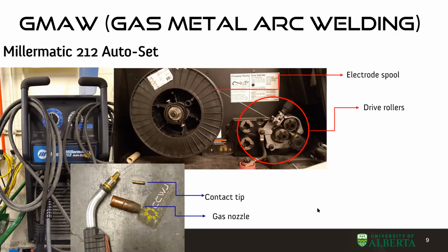So when you put down the electrode to be in contact with the plate, many bad things happen. Number one, you don't conduct electricity through glass until you push so much that you break the glass, and then the contact starts. And if you saw, not only was there an explosion, but the torch started to jump like crazy. That is because of the force of the wire pushing until it breaks the silicate. Then the arc starts, and then it fell, and it started to vibrate.